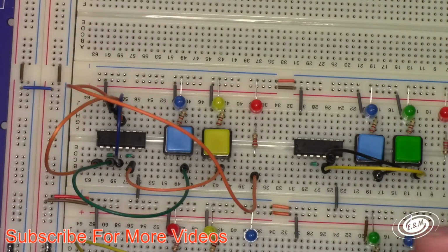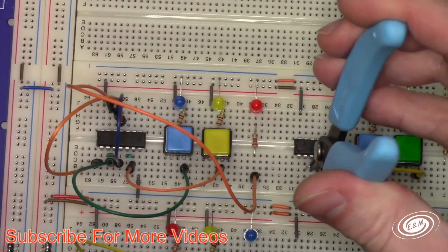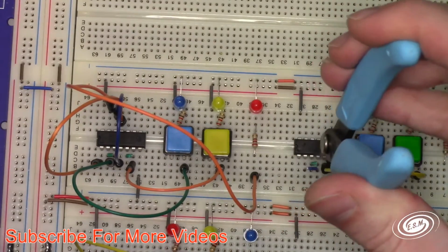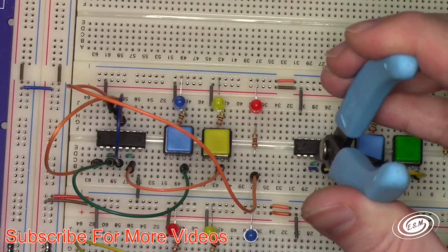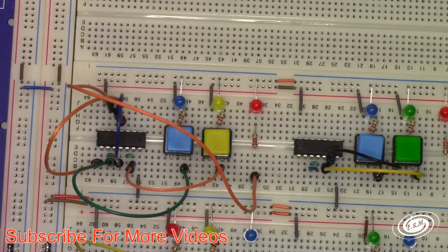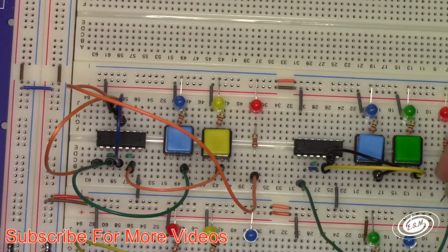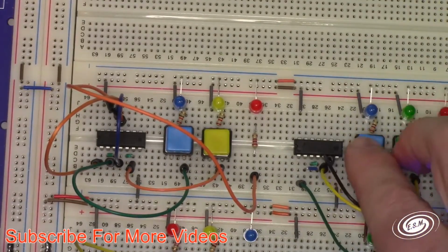I'll just tie it like this. Okay, so the output of that NOR gate is tied to the inputs of a second NOR gate, which is pin 2 and 3, and then I can take the output off of 1, plug it into my LED, turn the power on, and I have an OR gate.